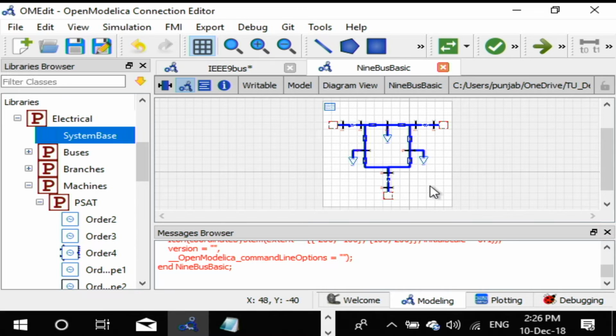If controllers are to be added, they will take up space on the network model workspace as well, crowding the entire model. The best way to overcome this is to create a separate model file that can represent a generator and all of its associated dynamic models, and then import this model file into the network model workspace.